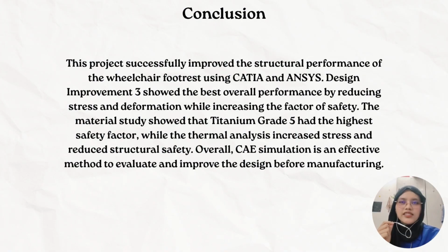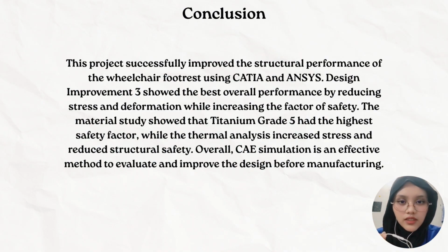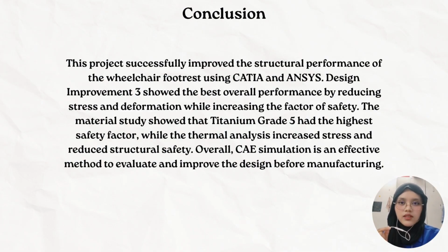In conclusion, this project successfully improved the structural performance of the wheelchair footrest using CATIA and ANSYS. Design Improvement 3 showed the best overall performance by reducing stress and deformation while increasing the factor of safety. The material study showed that titanium grade 5 had the highest safety factor, while the thermal analysis increased stress and reduced structural safety. Overall, CAE simulation is an effective method to evaluate and improve the design before manufacturing.